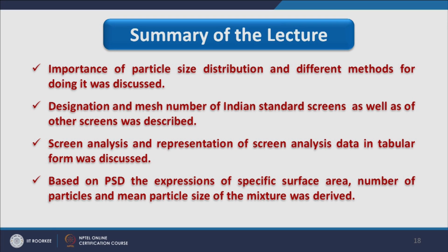And here I have the summary of this lecture. The importance of particle size distribution and different methods for doing it was discussed in this lecture. Secondly, the designation and mesh number of Indian standard screens as well as other screens was described. Screen analysis and representation of screen analysis data in tabular form was discussed, and finally, based on PSD, that is particle size distribution, the expressions of specific surface area, number of particles and mean particle size of a mixture were derived. So, that is all for this lecture. Thank you.